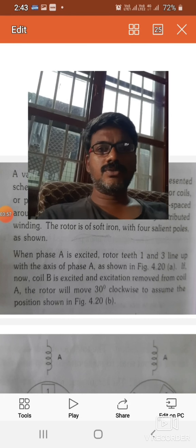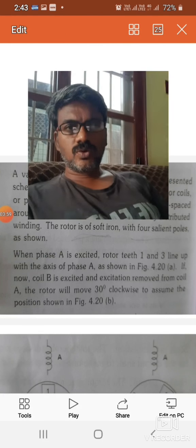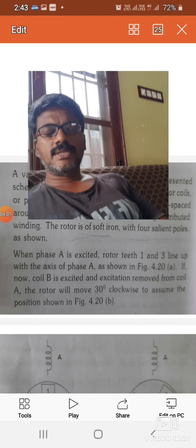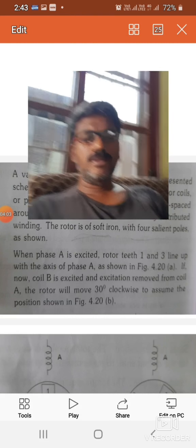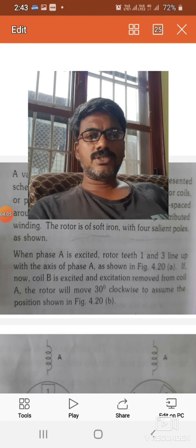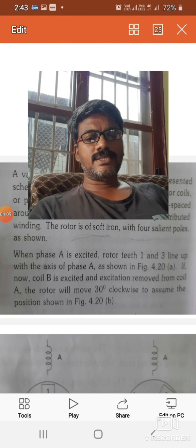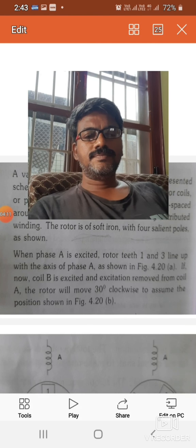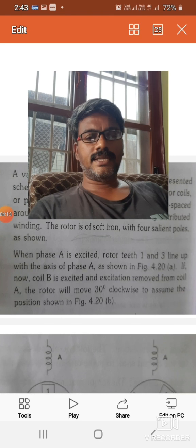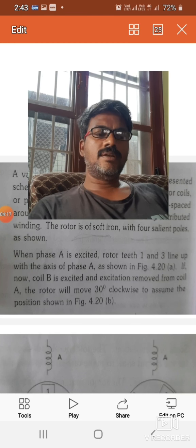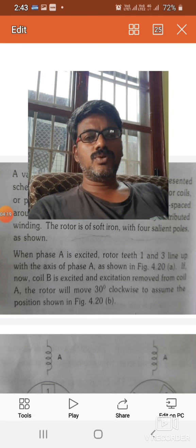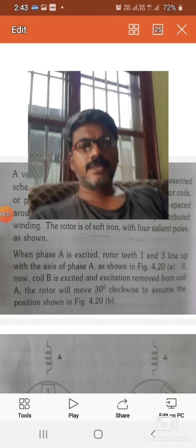Another important point, already discussed, is that there are two types of controls. One is the number of pulses, which determines the angle of rotation, and the other is the direction, determined by the order in which the poles are excited.